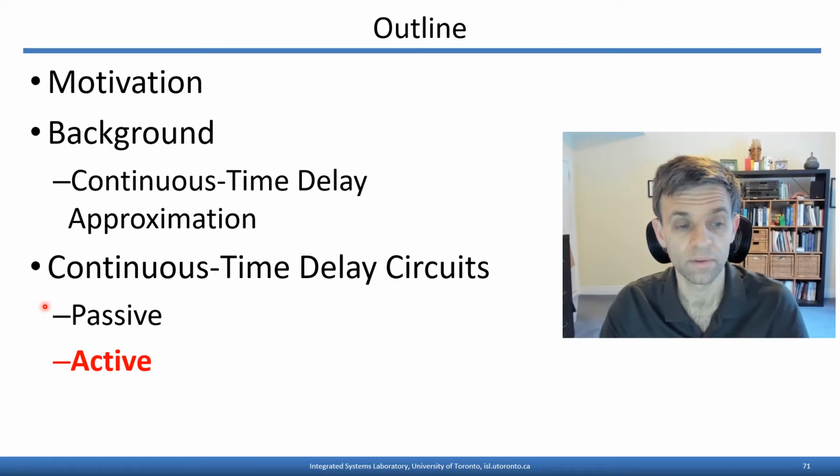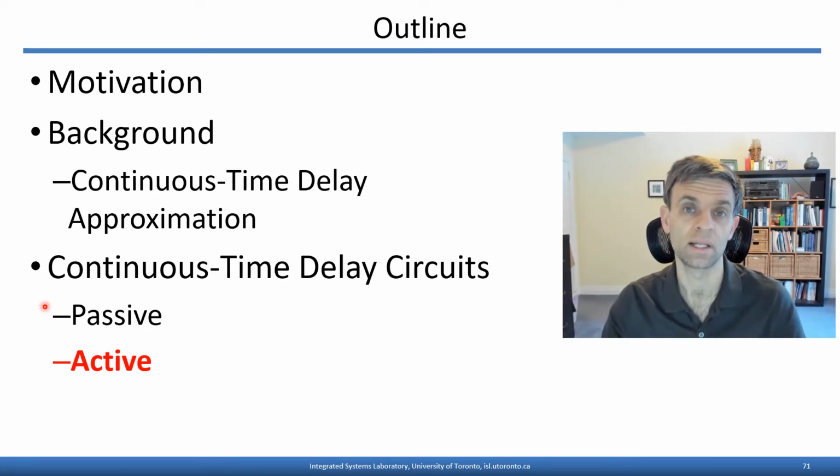And we saw that one of the main drawbacks with the passive elements is the fact that they use relatively large components, especially the inductors and or transmission lines. Now, technology trends, fortunately, are affording us better and better metallization in the high layers of the interconnect. These have lower and lower series resistance, lower losses associated with them. At the same time, as applications proceed to higher frequencies, we're more and more interested in relatively short time delays, which allow passive delay lines to become more compact. So these trends tend to favor passive delay lines.